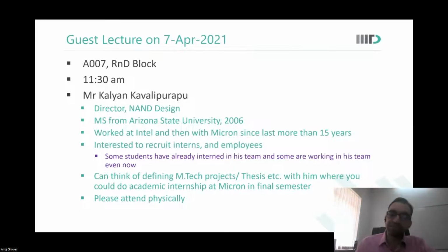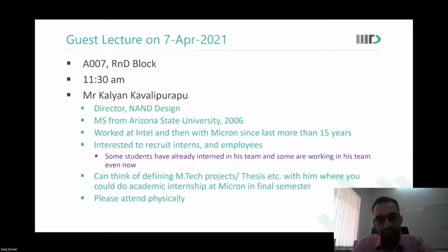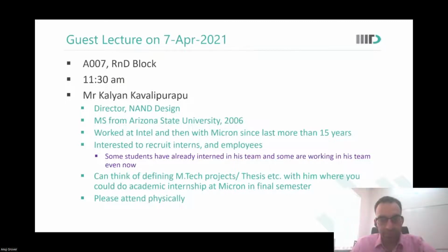So what were you doing in the last class? Let's see how many of you have already studied. We were looking into the non-volatile memories. We talked a bit about EPROM and EEPROM, and after that we were looking at Flash, and how we use the floating gate to change the VT of the device. Then we were talking about the VT curves, how the current will change, and we'll store four different 2-bit values. Till that much I remember. Anything else anyone wants to add?